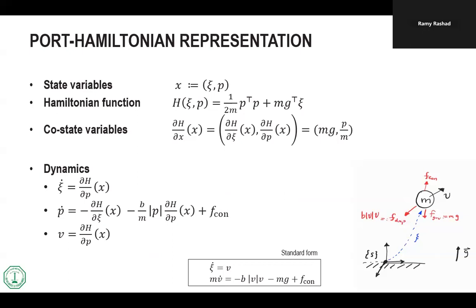Well, with the Port-Hamiltonian, when solving the mass spring or mass spring damper, the Hamiltonian function is the same, because the R matrix only appears in the second one. Yes, so the Hamiltonian is like the total energy anyway. Absolutely. So R doesn't appear in it. Exactly. It's the stored energy. H is the total energy stored in the system. Damping is something else.